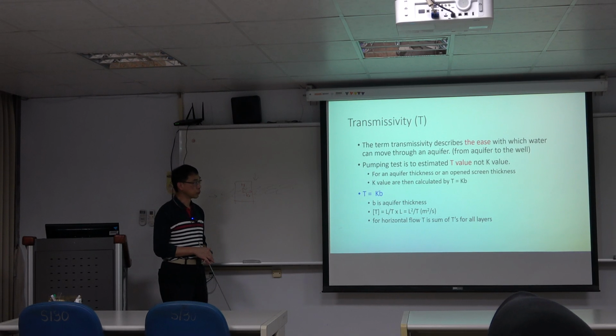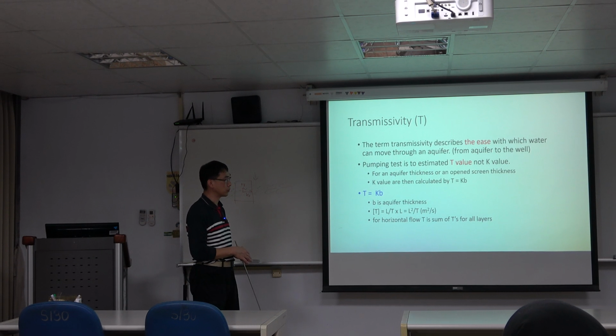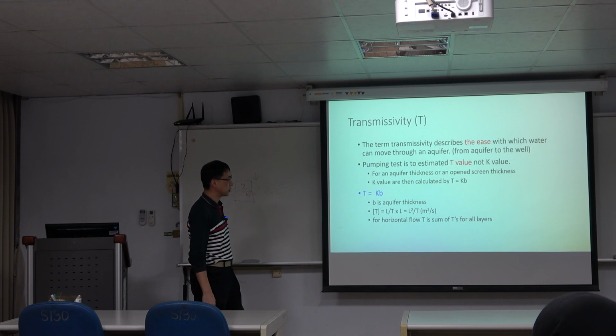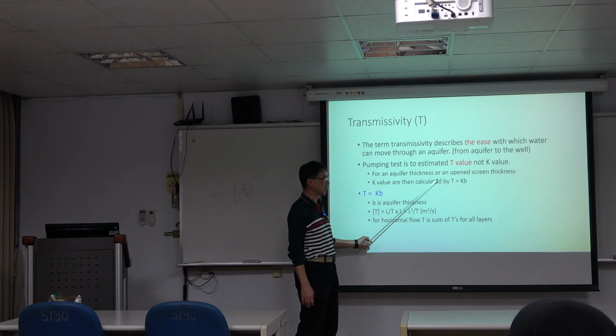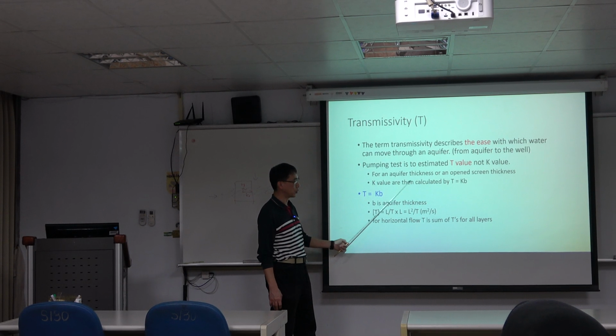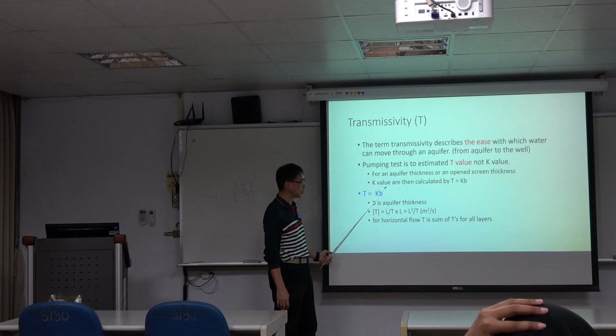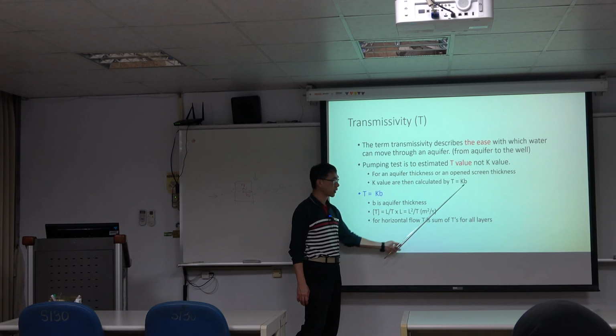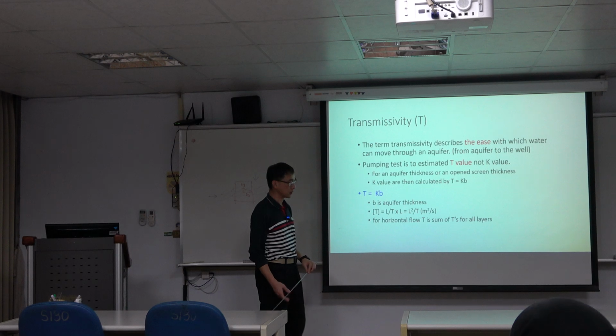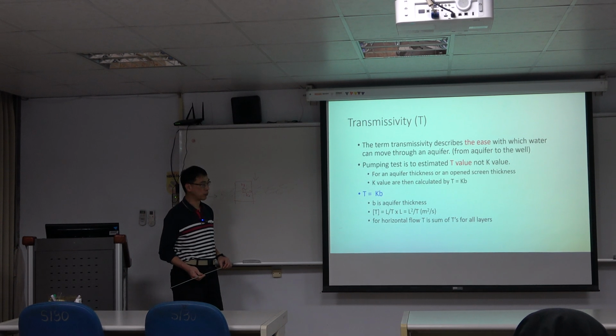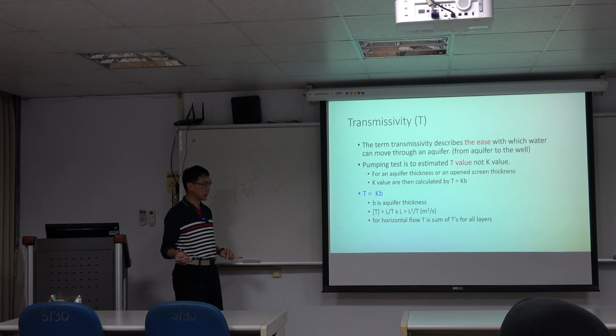And transmissivity, as we mentioned, describes a similar concept, but with the thickness included. So the pumping test is to estimate the T values, not the K values. For the aquifer thickness or open screen thickness, K values are calculated by T equal to Kb. Although in most situations in the numerical assessment we use the K values, not the T values, you should know that in reality we commonly use the T value for the assessment. But in the numerical models, we are not able to use T values.